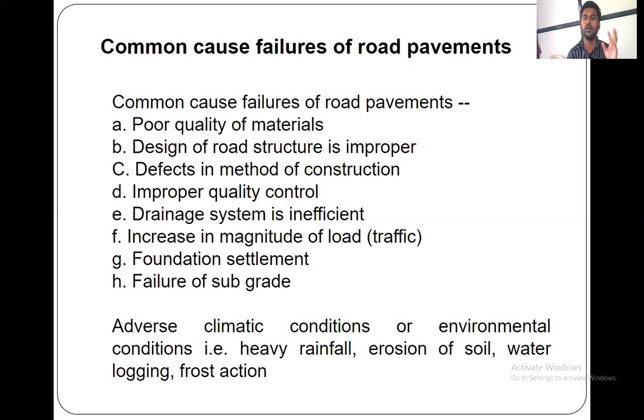You might have observed that due to heavy rainfall, the road slides away. Due to the soil erosion and waterlogging, suppose the water table gets raised due to heavy rainfall, then the waterlogging condition will be there. Then frost action: if water gets into the layers of the road, and the temperature goes below 0 degrees, and so on.